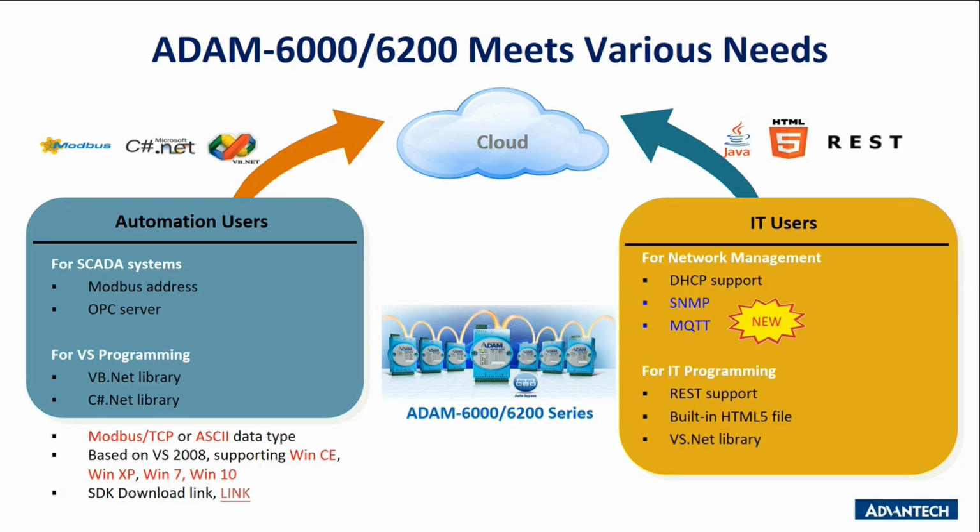As for the IT users, our I/O module also supports RESTful API and MQTT. SNMP is also supported and normally used by network engineers. And as mentioned just now, we do provide SDK for VB.NET and C# programming. And the software used will be Microsoft Visual Studio. You may refer to the link below for the SDK download.